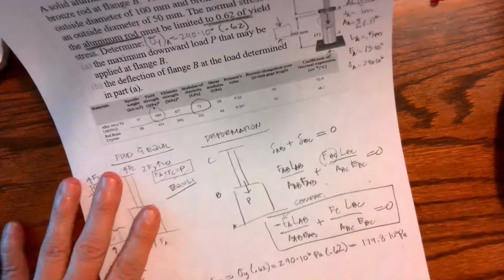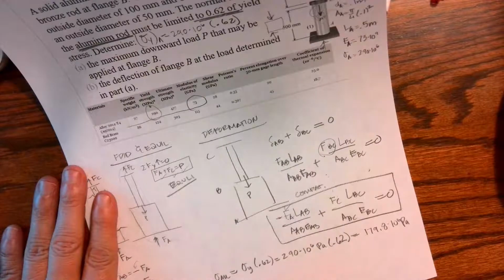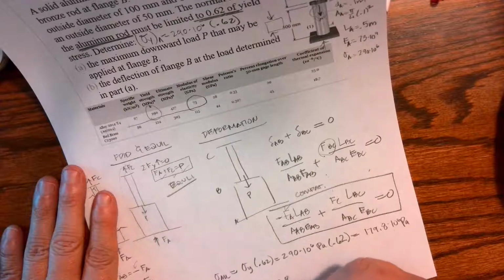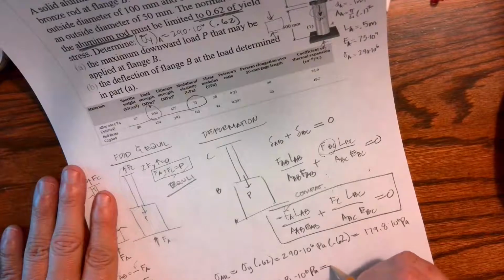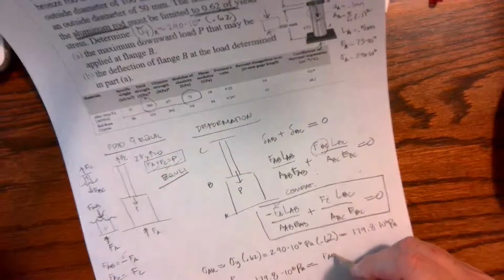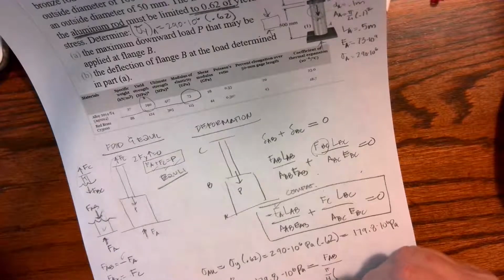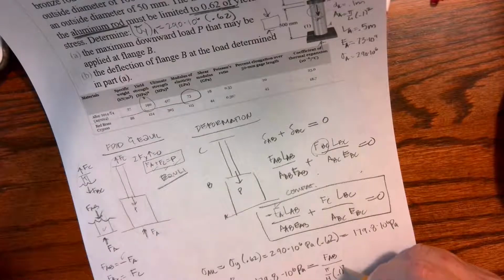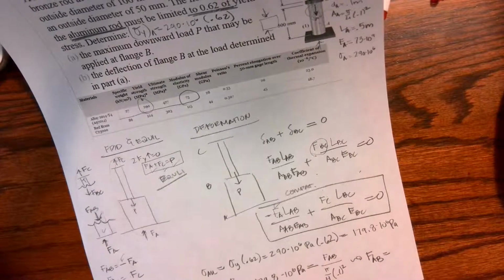Well, how is that stress related to these internal forces? Stress is just P over A. So I have 179.8 times 10 to the 6th pascals equals this force AB divided by pi over 4 times 0.1 squared. So I can find that my force of AB equals